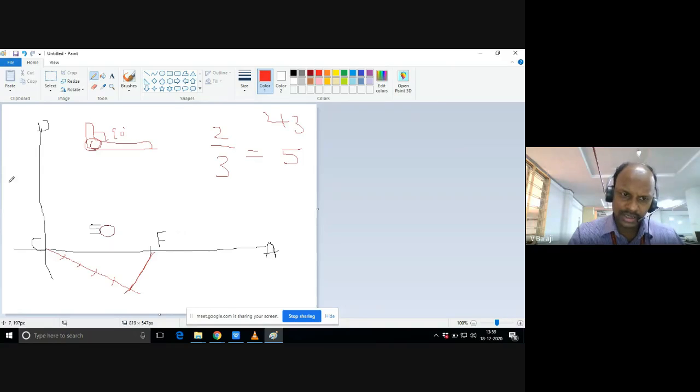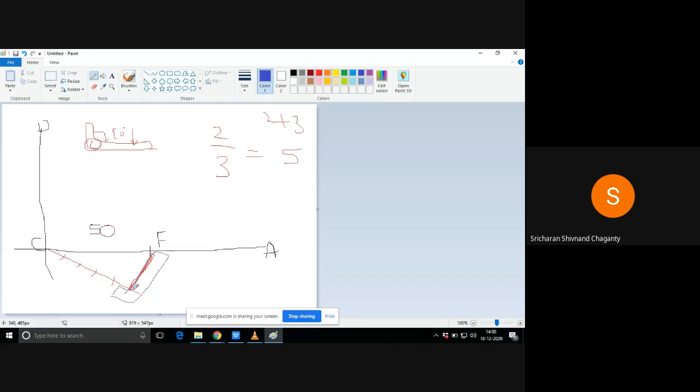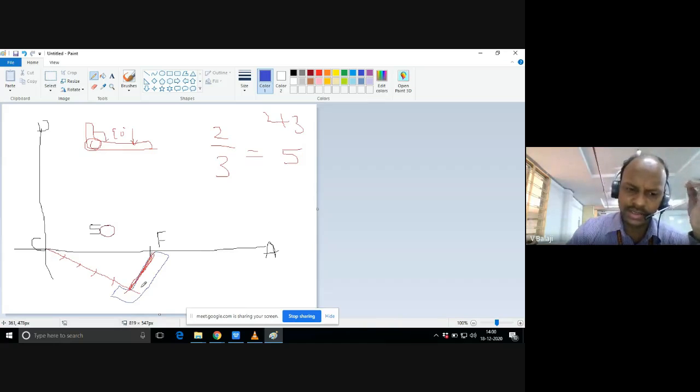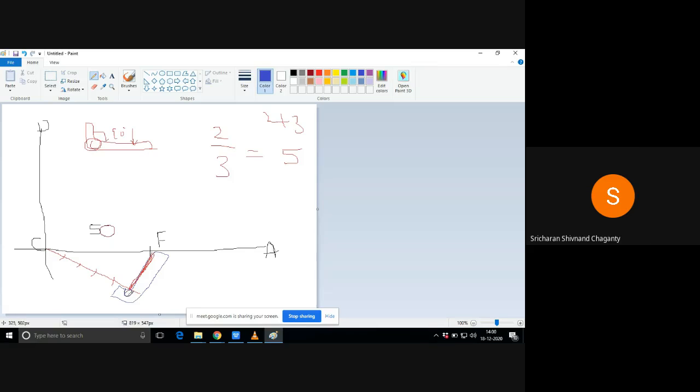So what you have to take is match your mini drafter scale, any one scale, parallel to this particular line. This line you can join with an ordinary scale. Match parallel to this line. Generally the longer scale you can match. And tighten the mini drafter. The shorter one shouldn't move, it should be in that position only.